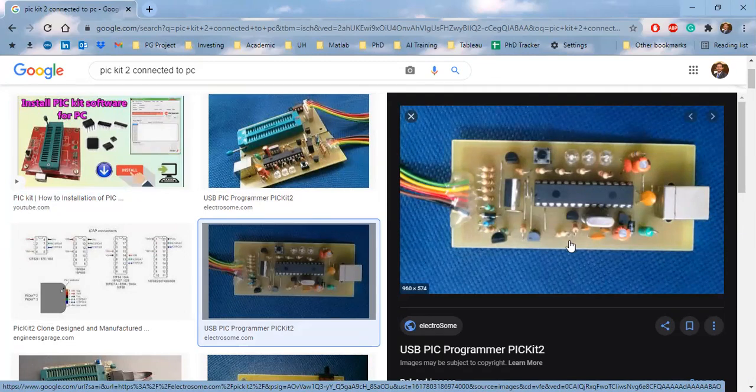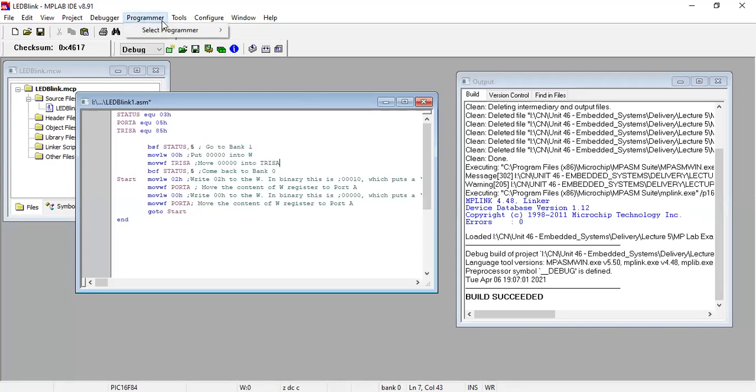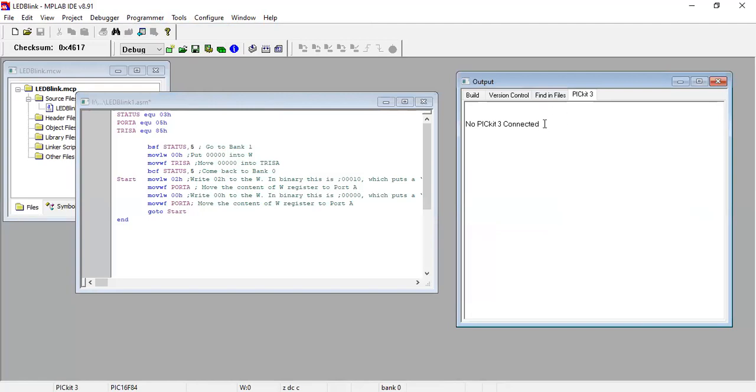So in order to do that, we can use this. Here, select programmer, right? We have to select PICkit 3. If PICkit 3 is connected, it will show, but here it is not connected, so I haven't connected one. Using this MPLAB, we can select that hex file and put that hex file inside our microcontroller, so it acts as a GUI for that.